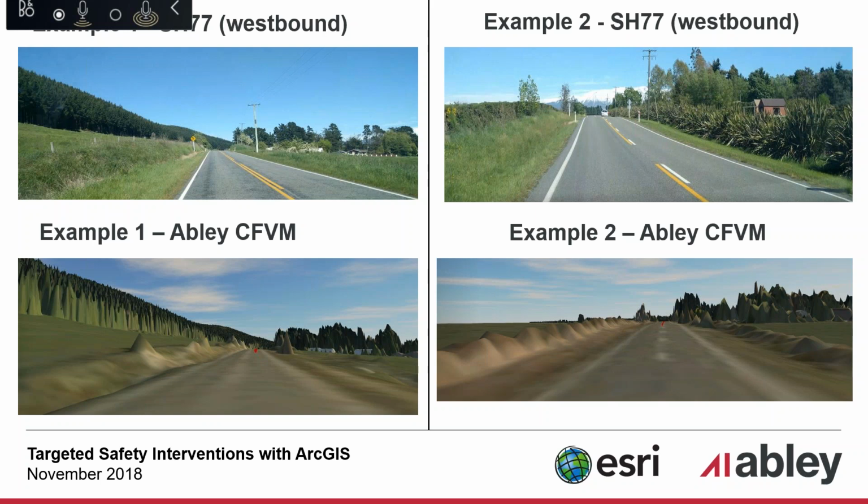One of the other things to bear in mind in New Zealand is our practice regarding no overtaking lines is that no overtaking lines are only marked where visibility or forward sight visibility is lost due to vertical terrain. So if forward visibility is lost due to a horizontal curve, the New Zealand policy is not to mark no overtaking lines.